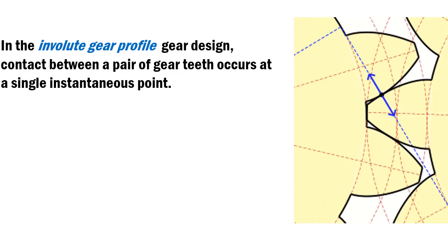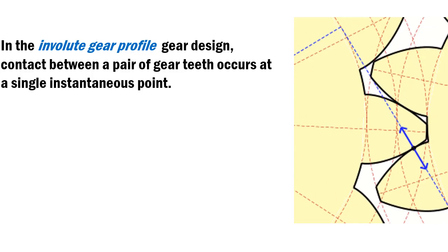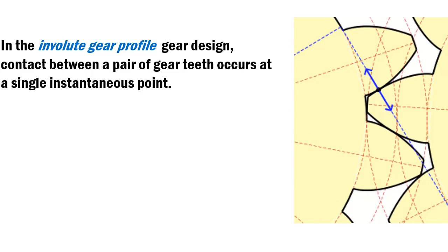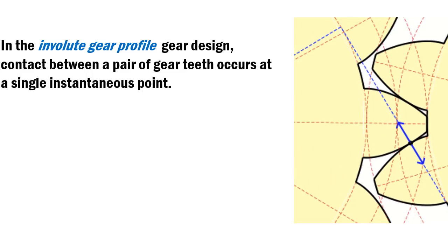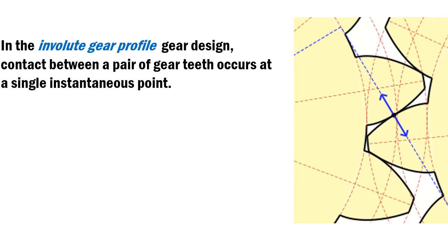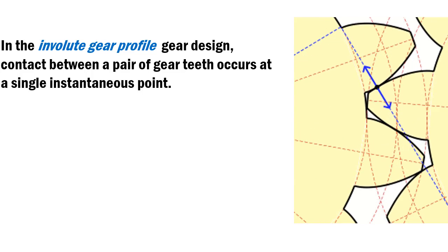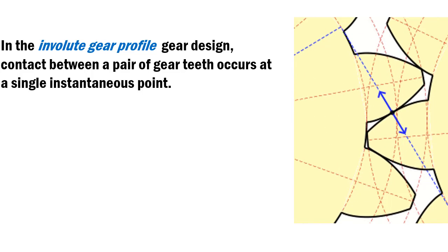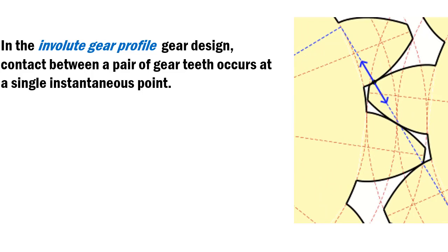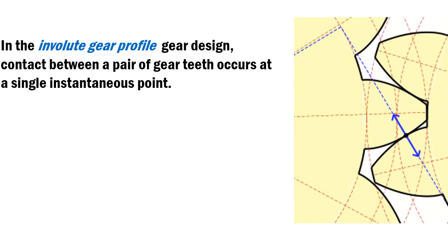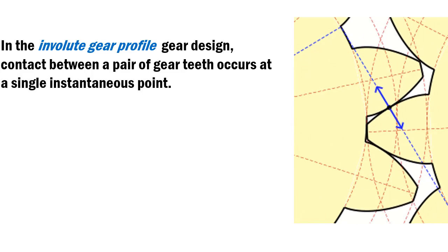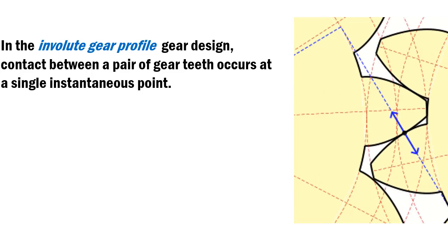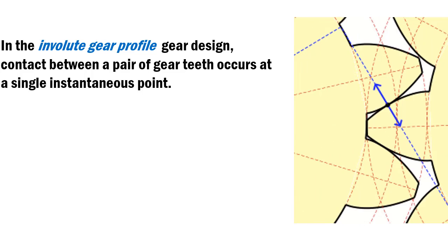And so now you can understand why it's so important for that smaller pinion to be much stronger, because that tooth has a lot of pressure. And they're going to be used much more often because there's a smaller number of teeth in the pinion gear than in the other main gear, or wheel, as it's called.